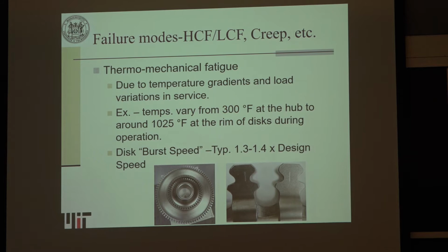In terms of the failure modes for these types of engine components, very important failure modes to consider include high cycle fatigue and low cycle fatigue. So every time you go up on a plane, you have a takeoff, you have cruise, and it goes through its various mission profile up to landing. So what happens is you have a pressure and depressure, which is a cycle. So every time you're on a plane, it undergoes cyclic stresses.